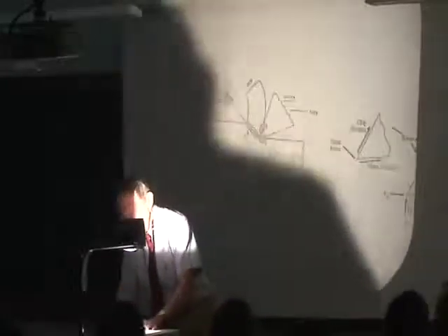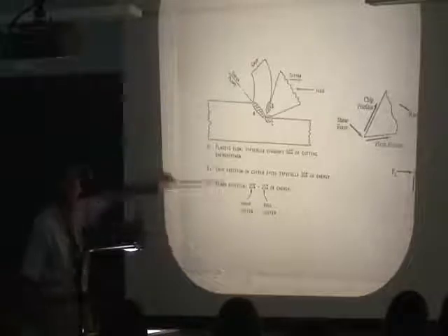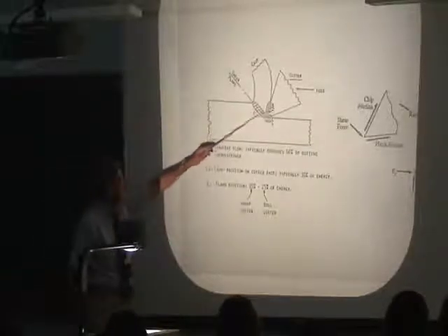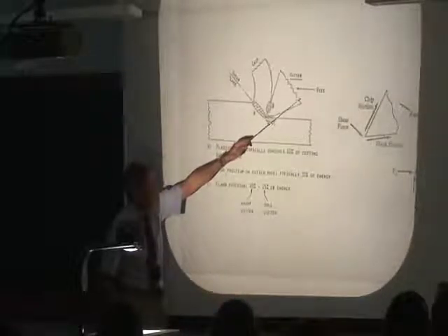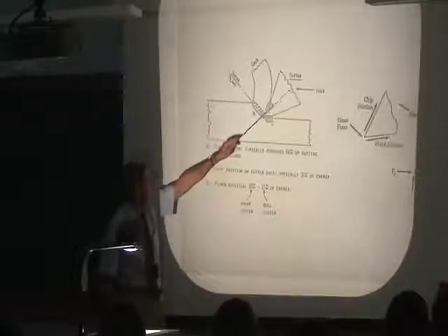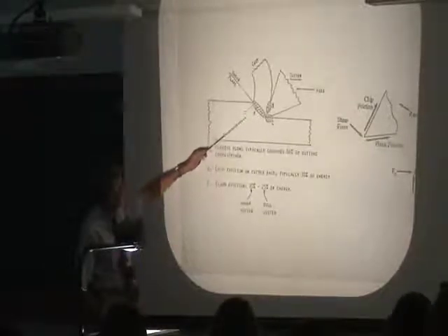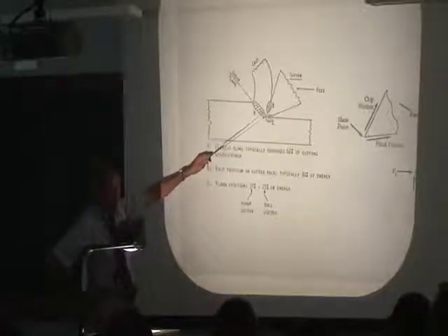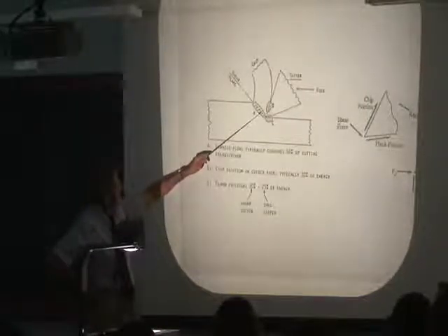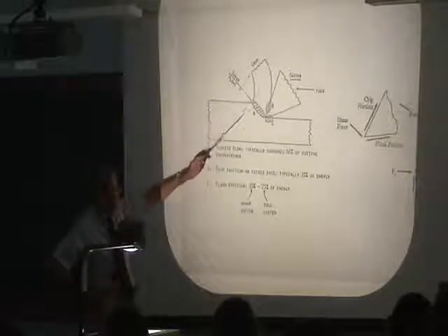All right, machining. What goes on in machining? Here's what the basic physics models are based on. You have a cutter, you force it into material. This is feed. You're pushing it here either manually or in a machine tool, a cutter, and you make a chip. So what happens here is you create a shear zone. The material first deforms plastically, then it deforms elastically, and finally you push it way past its yield point and it breaks, and the chip breaks off.